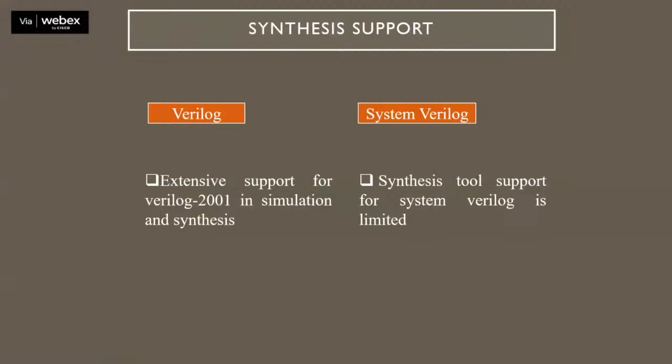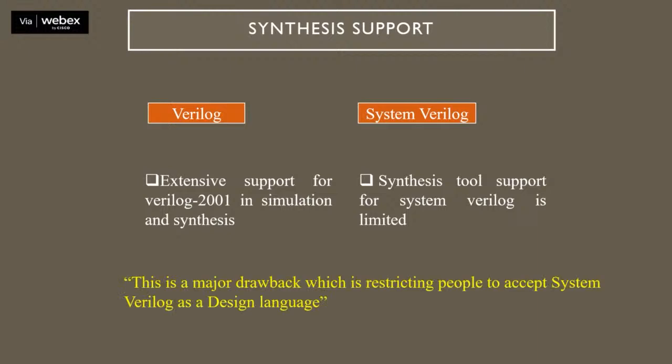But when it comes to System Verilog, you have very limited synthesizable tool support, and moreover, when you use System Verilog for implementation purposes, the smart usage of synthesizable constructs becomes a limitation. So that is one of the major hindrances in accepting System Verilog as the design language.